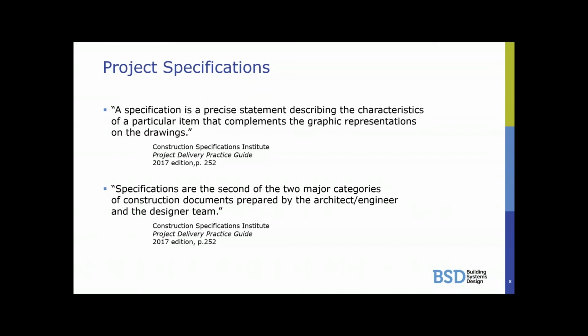They're produced by the design professional and consultants. There's standard organization and formatting, of which we spoke, numbering system, the 50 division MasterFormat, the section format, which is organized in 3 parts, general, products, and execution, and a page format, which is an outline format that makes it very readable and easy for the parties, especially contractors and subcontractors, to find the information they need in order to proceed in construction of the facility.